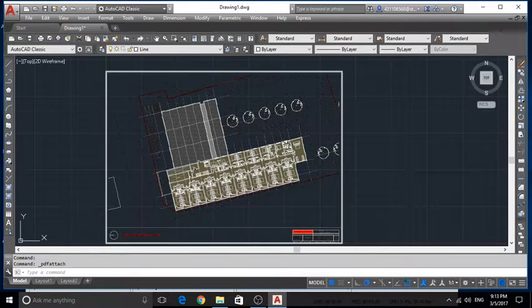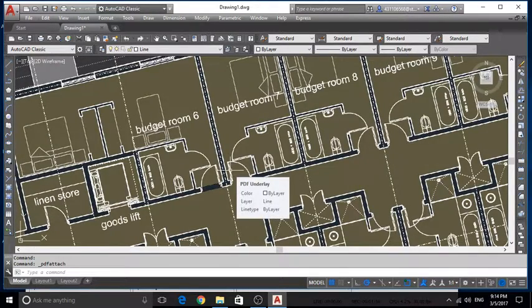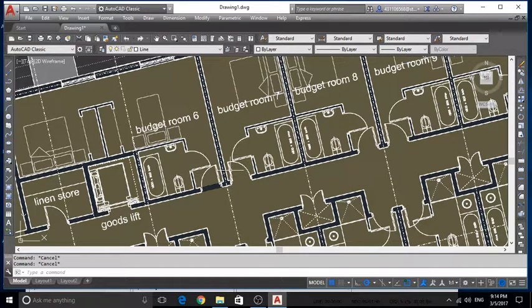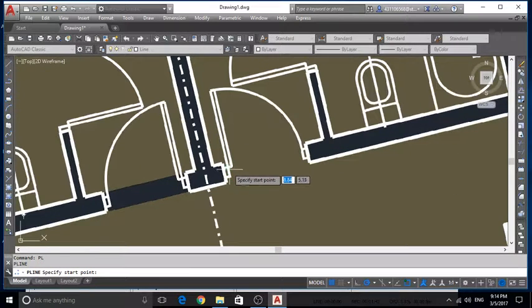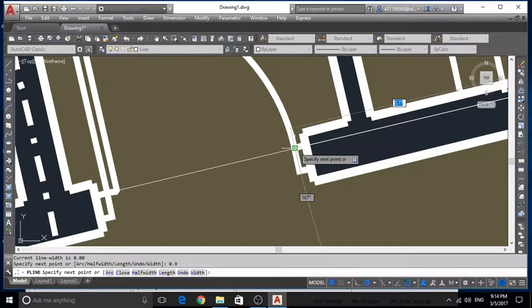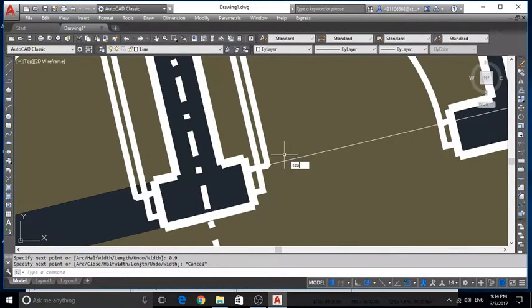But we're just going to scale it right now to millimeters. Yeah, I'm just gonna scale it to millimeters, but first off we're just gonna press PL for polyline, and I'm just gonna press on the endpoint and to the other endpoint. Let's say it's this one, and I'm just gonna type in 0.9 meters, and then I'm gonna scale that.